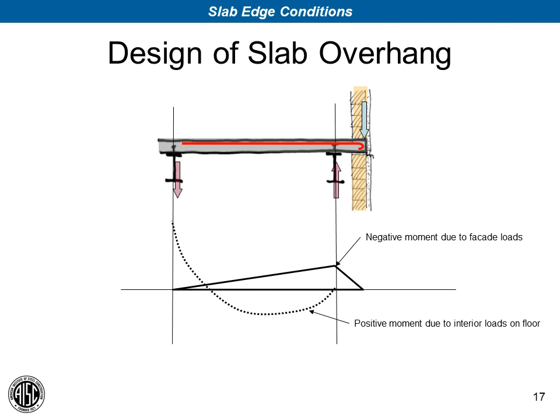I see. I suppose that you could do that, though it's probably not going to be particularly economical in terms of coordination of the reinforcement in the wall. And in addition, I think you'll still have some negative moment over the spandrel beam that you have to contend with, and providing reinforcement in the slab to do that.